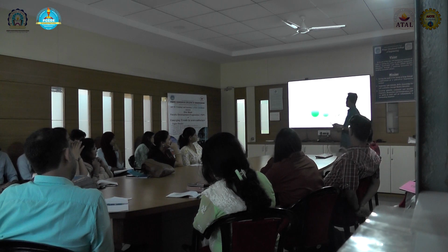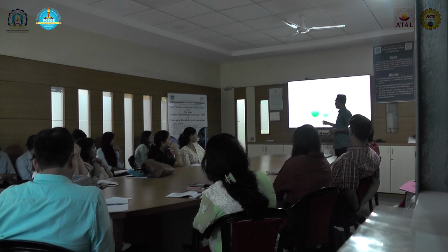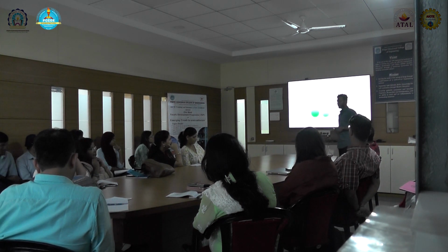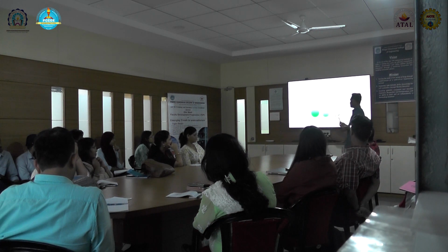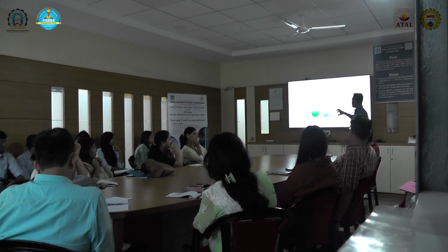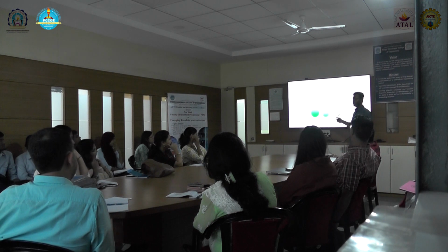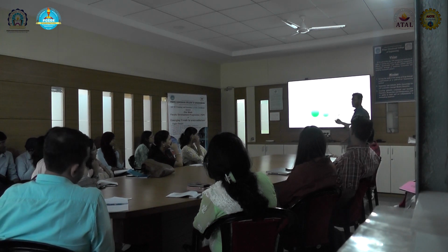This indicates the types of assumptions we will have. We can have a simple spec where the whole behavior is legal. Then there can be 2 modes, where only one of the modes is enabled. So this would be a simple assumption set. But then there comes a complex assumption set. Even within the documentation, there are many legal inputs and many more sequences which we need to provide to formal in order to verify all the outputs. This is required. If we don't have this, it will just point out where the legal behavior is not correct.